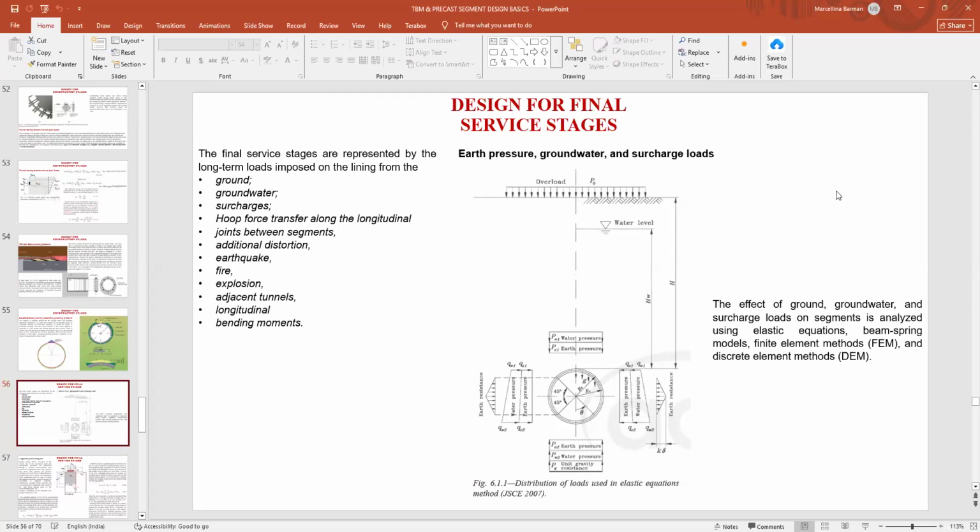Now, all our metro projects are generally at a very shallow cover. We have a 20 to 50-meter depth. So our grouting pressure varies between 1.5 to 2 bar. Sometimes we provide 0.5 bar, 1 bar pressure. But in a TBM, these grouts are mostly backfill grouts. So we are not going for very high compressive strength grout because we are just filling the gap between the excavated face and the segment at the tail end.